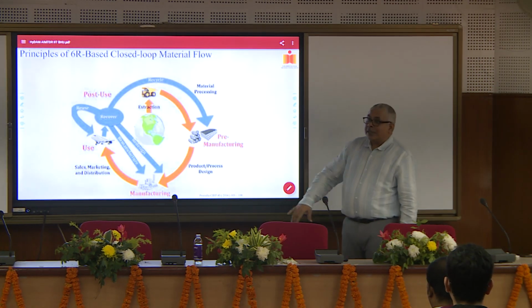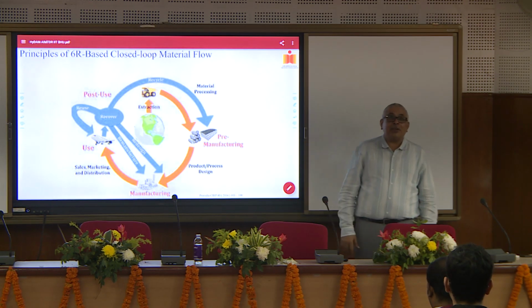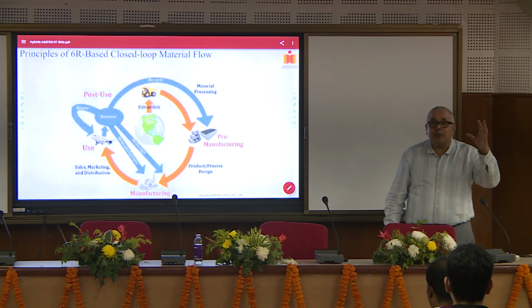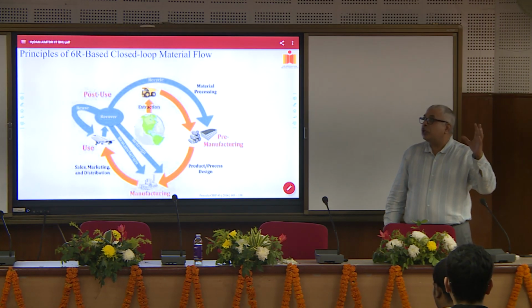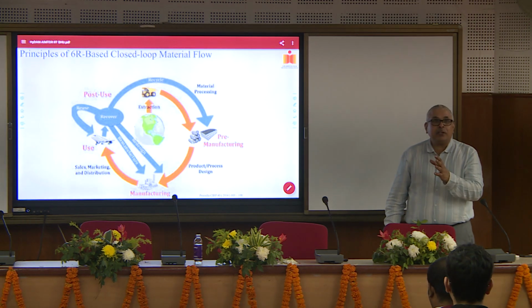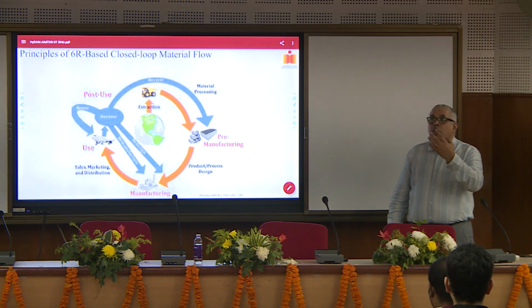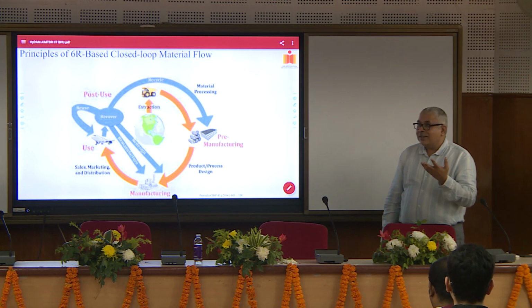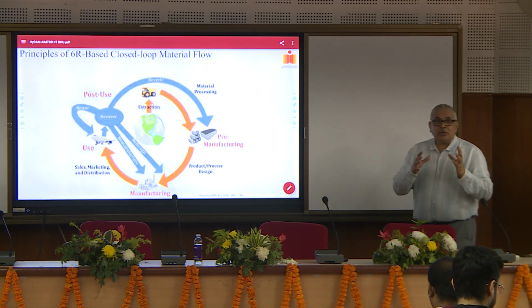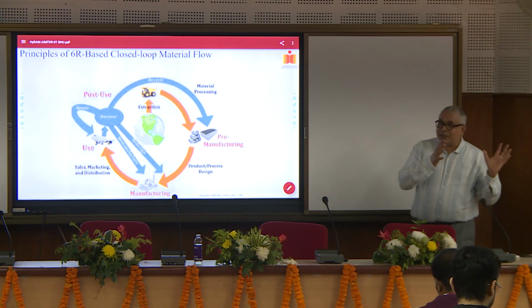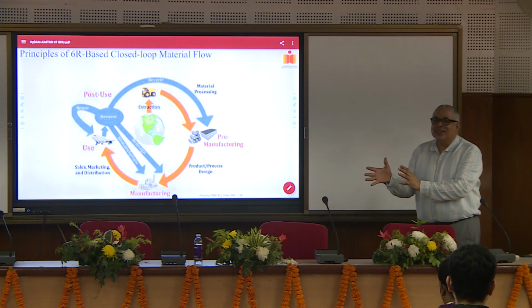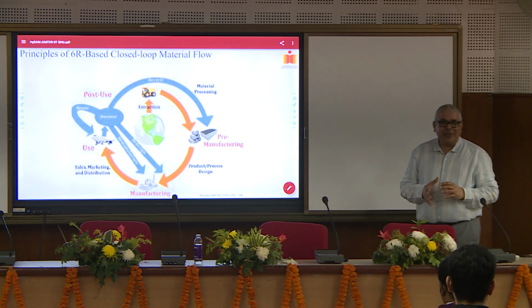Okay. Here, additive manufacturing helps. Whenever you are designing a new part, conventional manufacturing processes will not help you to produce whatever geometry you want. But the additive manufacturing processes will allow you to optimize the part geometry using topology optimization, so that material is present only wherever it has to be. Okay, you can deposit there. So this is where additive manufacturing is useful. At the same time, additive manufacturing cannot be used wherever you want. This is the point which I just wanted to communicate here.